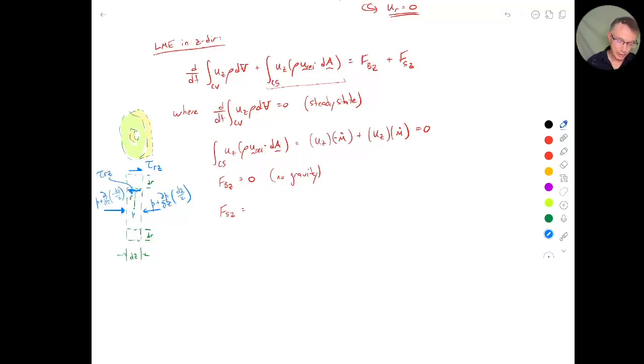It's on the radial face pointing in the z direction, so that the one on this outer face will be the shear stress I start with here, which is tau rz, plus how much that shear stress changes as I move in the radial direction times how far I've moved to get to that outer face.